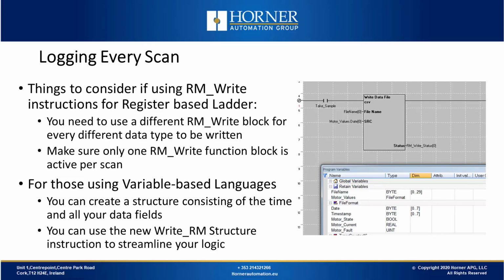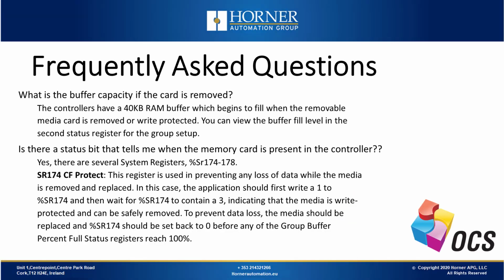There are some things to consider if you're logging every scan. If you're using register-based ladder, then you need to use a different removable media, or RM, write block for every different data type to be written. And make sure only one RM write function block is active per scan. If you're using variable-based languages, you can create a single structure consisting of the time and all of your data fields. You can also use the new write RM structure instruction, which will streamline and minimize your logic.